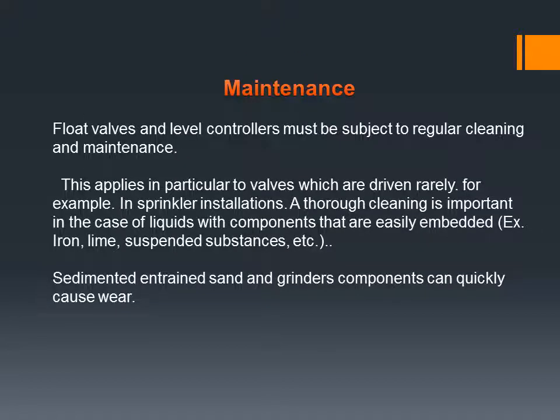Maintenance. Float valves and level controllers must be subject to regular cleaning and maintenance. This applies in particular to valves which are driven rarely, for example, in sprinkler installations. A thorough cleaning is important in the case of liquids with components that are easily embedded. Sedimented sand and grainy components can quickly cause wear.